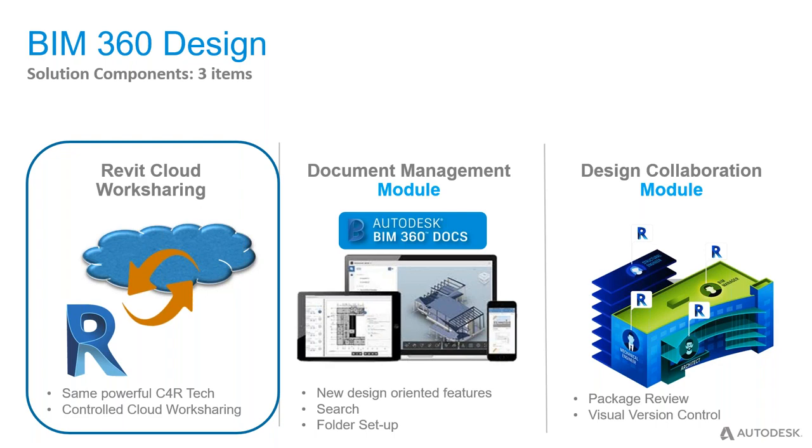I tend to say if an IT manager would in the background remove Revit server and put the central files on BIM 360 Docs and Design and give everyone a local copy in the weekend, and Monday morning they start again, if they don't look at where they're saving to, they wouldn't know there's a change actually. So that's how easy this is to implement, if you will. So Revit Cloud Work Sharing, still the same philosophy for all of those architectural designers, structural designers, etc.